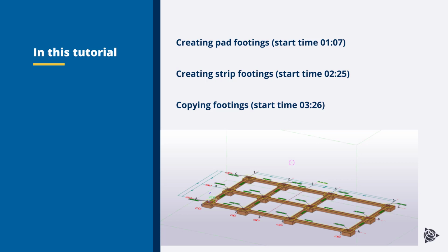In this tutorial, you will learn how to create the foundations for a model. You will create pad footings and strip footings. You will also learn how to copy objects with the commands Copy and Copy Linear.